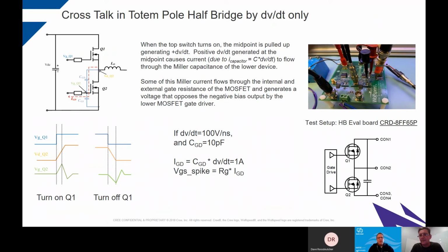Okay, gotcha. Now, is there an effective way to reduce these voltage spikes on the gate? Yes, there are several ways. Common sense ways, to be honest. Nothing rocket science, Kirk. Good layout, very good layout. Watch those source inductances. Watch the package source inductance, the trace source inductance. Keep the coupling nice and tight. That's common sense. You would do that with any switching circuit anyway, wouldn't you?